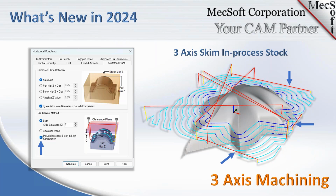But what this enhancement does is it actually also introduces the in-process stock in the computation. So if you had a roughing operation done previously and there were chunks of stock where you have the arrow on this picture, let's say there was actually in-process stock in the way.